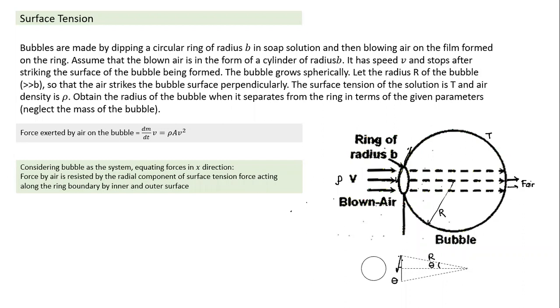So whatever force acts here, basically, what will be the x component? The x component will be, if we get dF, dF into sine theta. Whatever force acts on a small element, dF into sine theta. Sine theta is constant, so the net force acting in the x direction is equal to the total force into sine theta.